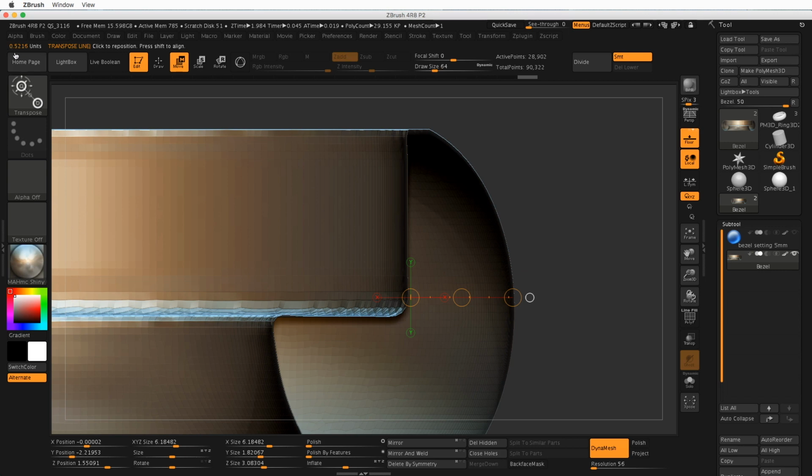So what I see here is that this is about 1/2 millimeter wide, which is a little bit thick for a bezel. So if you think about it, 20 gauge wire is 0.81 millimeters wide. So this is less than 20 gauge, so it's probably somewhere in, I don't know, maybe the 22, 24 gauge thickness. We could look that up, but for now we'll just leave it. So 1/2 millimeter is the distance we've gotten. However, I might want to beef this up a little bit.